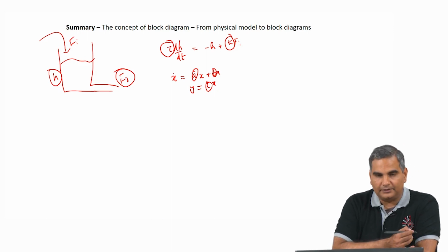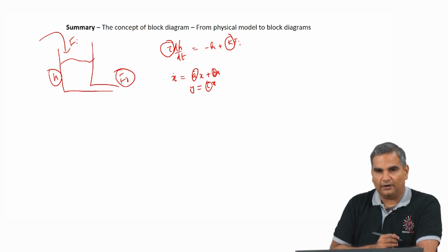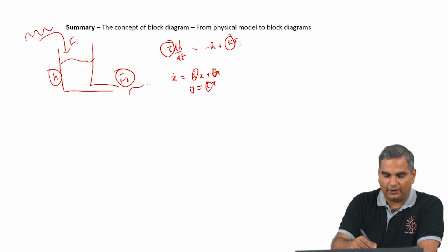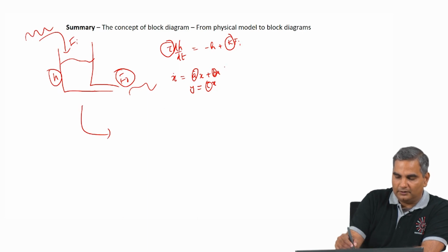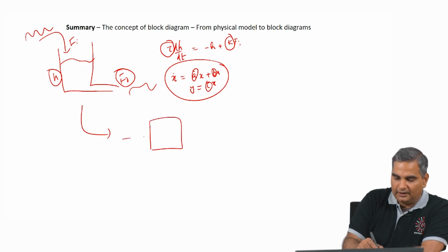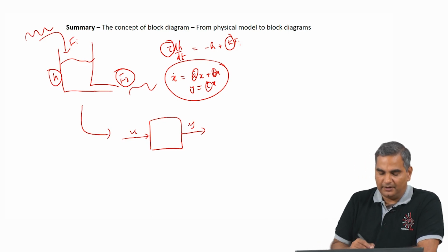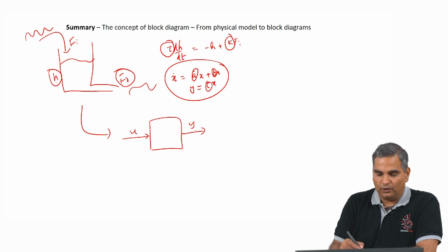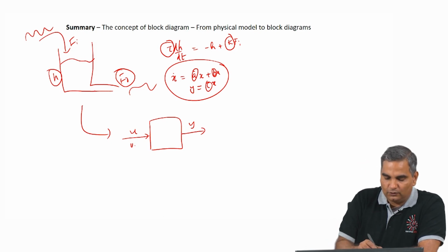So, if you really draw a picture like this and then say, how do I understand changes in flow affecting, let us say, changes at the outlet flow rate, your notion is basically there is some time profile that is happening for this, and I want to know what happens at f naught. Okay. Now, when we do a mathematical model something like this, then in the time domain, if I put in a block like this here, then I might say there is a u that comes in and a y that goes out. And when I write a block like this, then basically what I am saying is this u is some time function and this y is some time function, and I want to know how y changes when u changes. Okay. So, though I just write u and y, this is u of t and y of t.